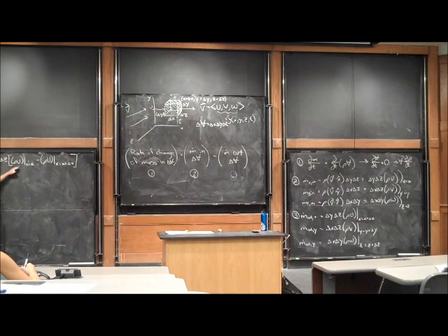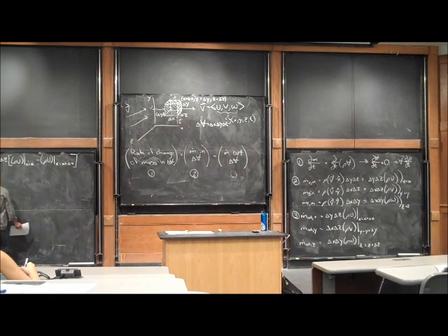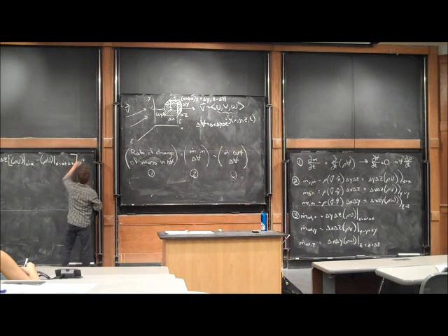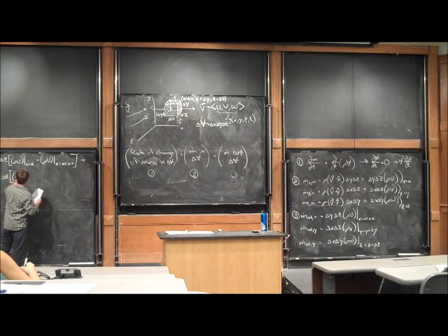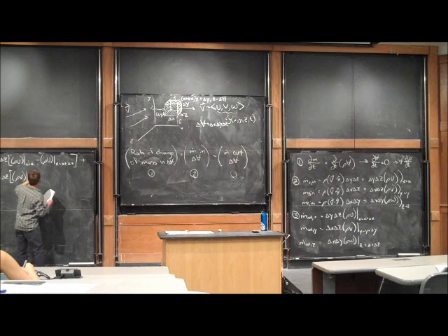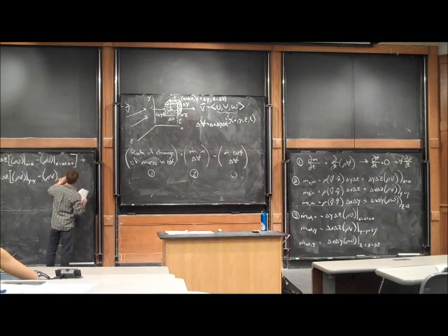So now this is where we're beginning to see the volume coming in and the volume coming out are not going to be the same because rho u is going to have a different value at a different location in x. Similarly, it's also going to be this whole term plus, in the y direction, delta x, delta z times rho v at y is equal to y minus rho v at y is equal to y plus delta y.